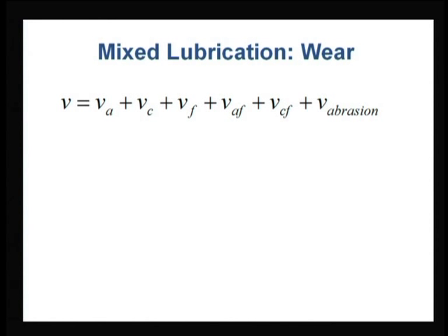First, in dry conditions there is a possibility of strong abrasion and strong adhesion, but when we talk about wear in lubricated conditions, there is a possibility of some sort of adhesion where the asperities are still in contact, some sort of corrosion, maybe the lubricant is corroding the surface or some process fluid getting mixed with the lubricant causing the failure, and finally comes fatigue. Fatigue will always be there. In lubricated wear, adhesion can be avoided, abrasion can be reduced, but fatigue will be the dominating factor in that situation.